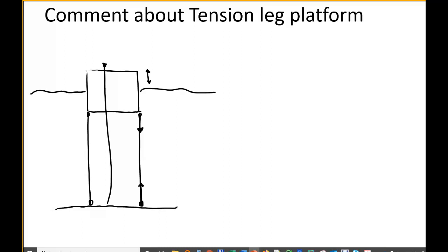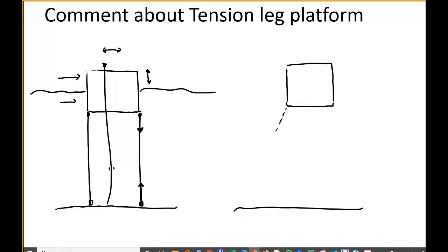The more important thing is that you don't want any damage occurring on the pipe, okay, on the riser. But it can actually have movement horizontally, okay, to the right. If, for example, you have waves impacting on this side, it can move to the right. The thing is that the TLP has a self-balancing mechanism. When that happens, okay, when you have pushed it slightly off its equilibrium position, for example, let's say you push it to that side, well, you see what happens with the tendon. Okay, now the force is always going to be aligned with the tendon.